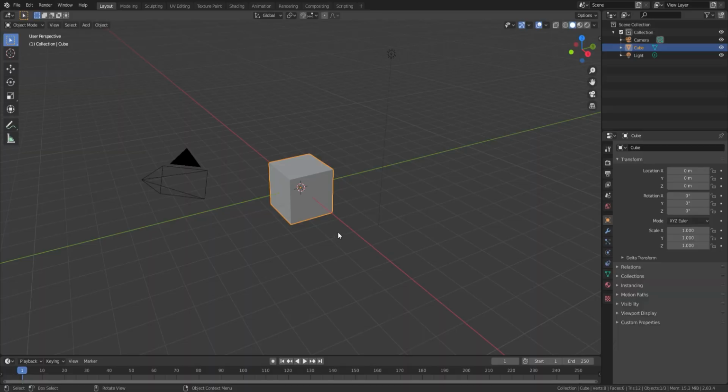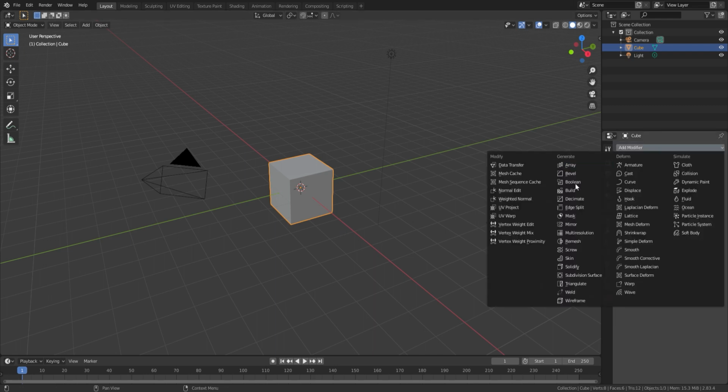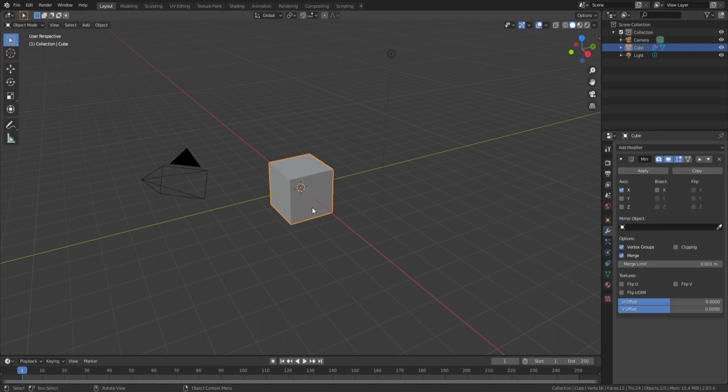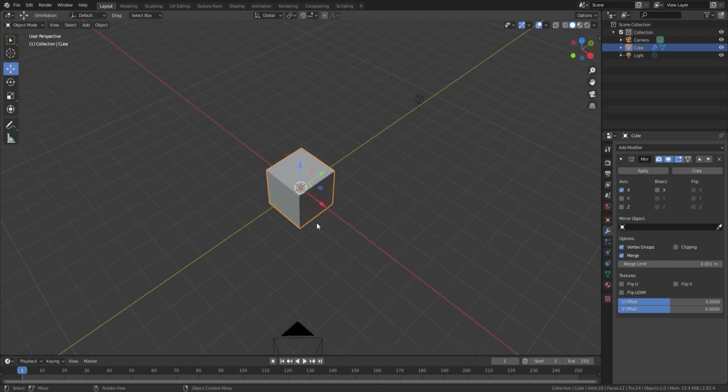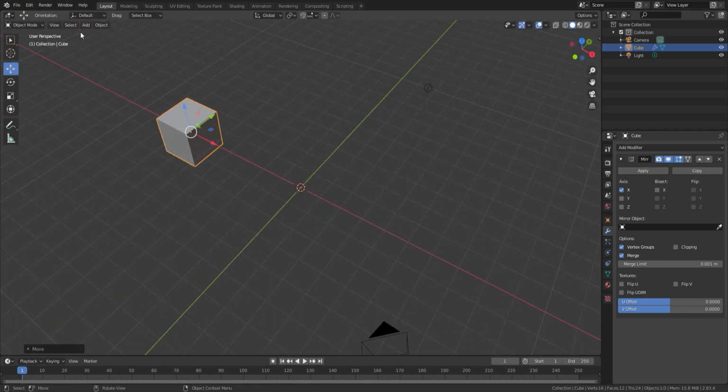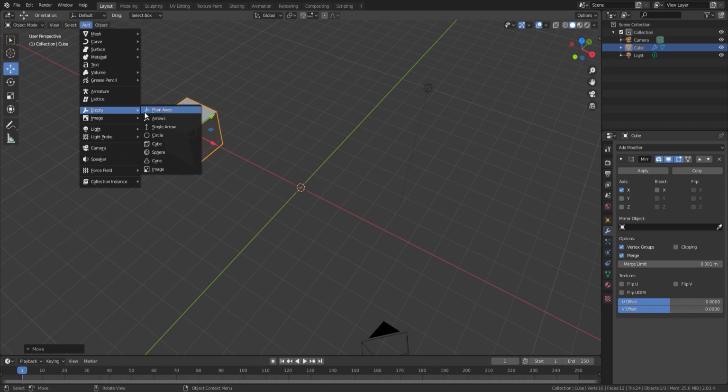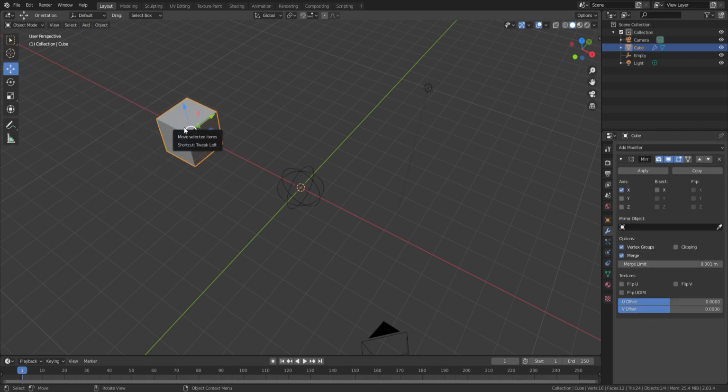By adding the mirror modifier, we are able to do limited replications. Let's add a mirror modifier to the object. For better visibility, let's shift the object, then add empty object to it. We switch back and at the mirror adjustments, we pick the added empty sphere. Set the exact location on the axis for the mirroring.